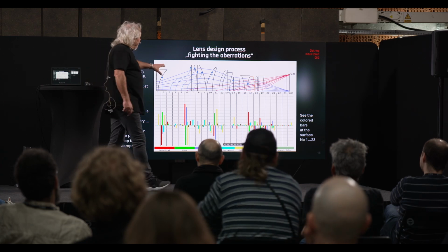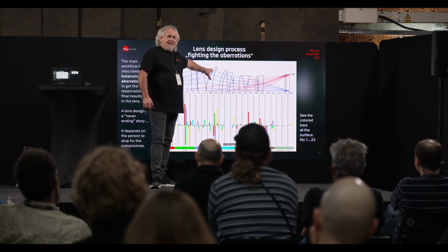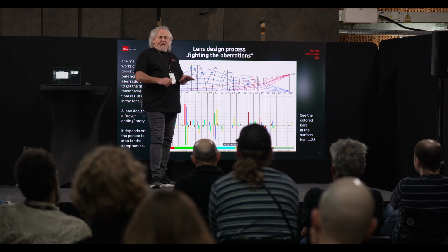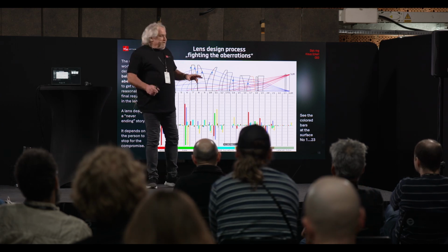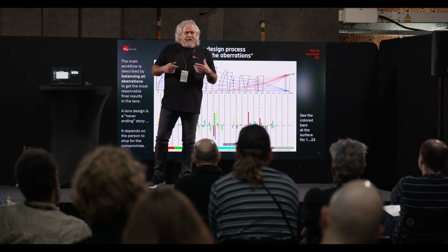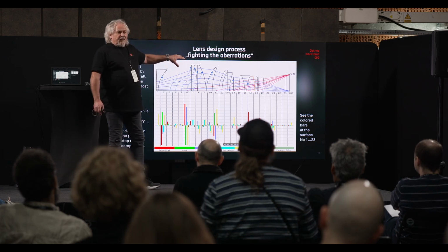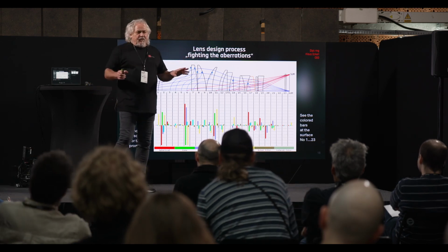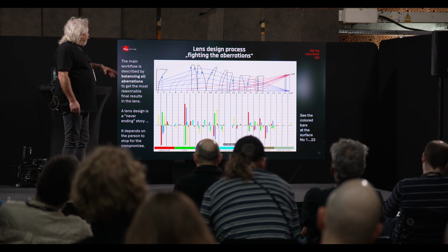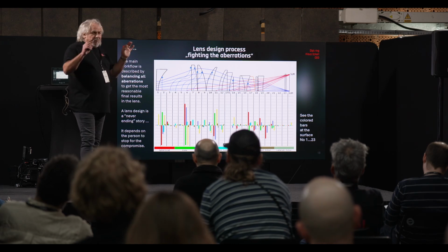You need to be clear that you finally have to move to align these lenses in your final process, because normally nothing is without any tolerance. So these candidates you have to align finally in your optical process. Otherwise you will never reach the design quality. You will never have zero tolerances on that. So as an experienced designer, you can immediately say, oh, this and this lens might be troublesome.